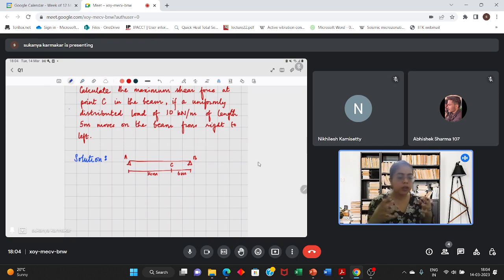in ILD, what are we drawing? Basically, there is a moving load. We consider it to be a unit load, a load having unity value. A unit load is moving on the beam, and we try to calculate the various responses of the structure.